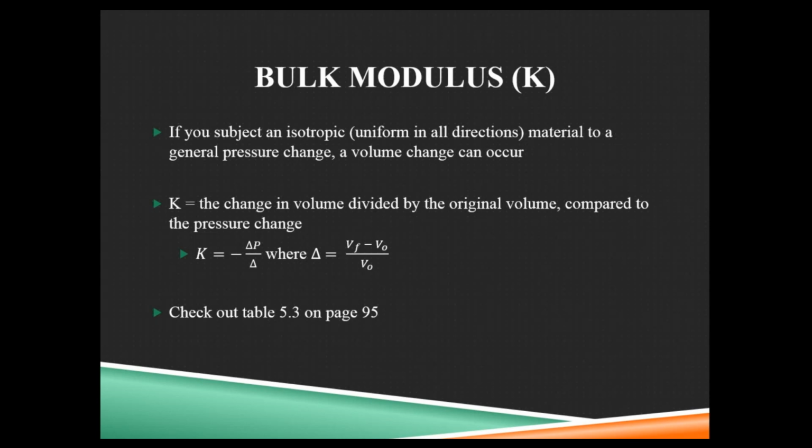This will cause a volume change. Remember, isotropic stress, volume change. Deviatoric stress, shape change. So when we have this general pressure, whether it's increasing the pressure or decreasing the pressure, a volume change can occur. Some materials are incompressible or nearly so. A lot of materials will change size.